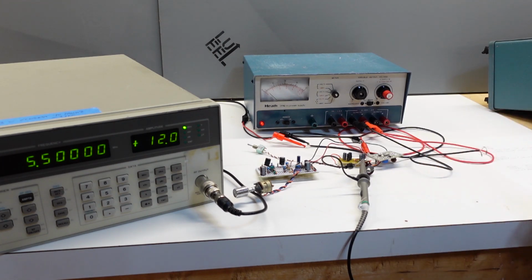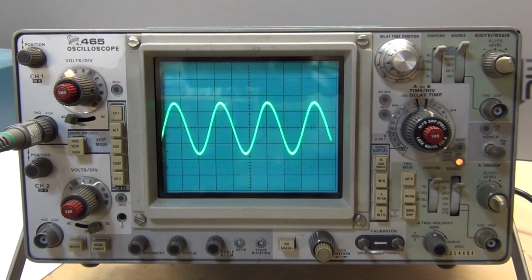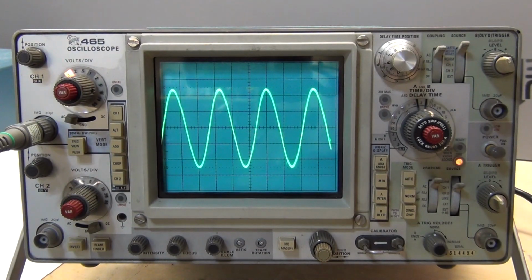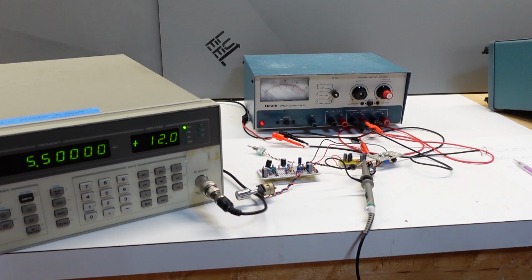And I'll switch the camera over here so we can see the 465. Reset it, of course. It's now 1/10 of a volt on the vertical axis, and I dialed the time base way down so we can see it. And right now I'm just under 200 millivolts peak, so just a little bit of extra gain should get me there. So I can adjust the signal coming out from the audio signal generator and also the audio amplifier, and crank it up and get it just in between those two divisions. So that's pretty close. That's about 250 millivolts peak. So I've got the audio input all set now.